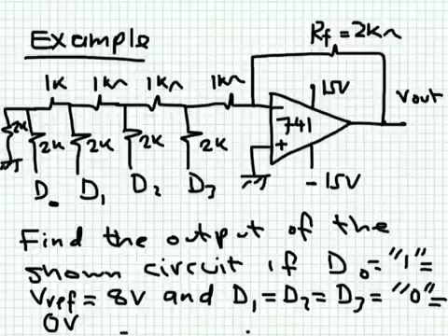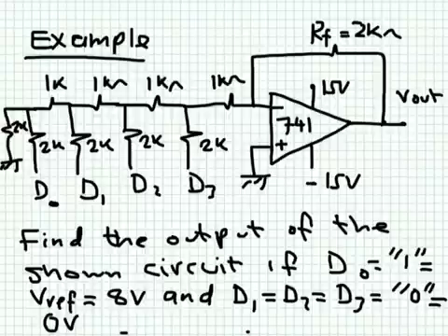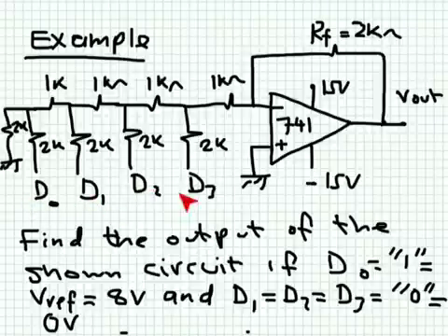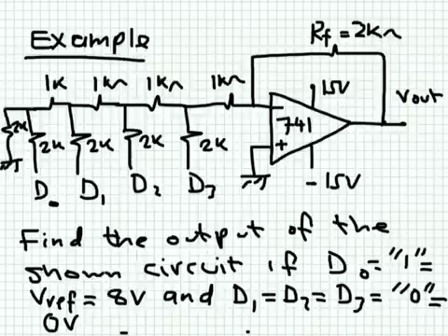Okay, let's take a look at an example. It's easier to illustrate through an example. So here we have a 4-digit digital to analog converter. As we agreed, these digits start to count from 0, 0, 0, 0, then 0, 0, 0, 1, 0, 0, 1, 0, 0, 0, 1, 1, 0, 1, 0, 0, and so on up to 1, 1, 1, 1. These are 16 binary numbers.